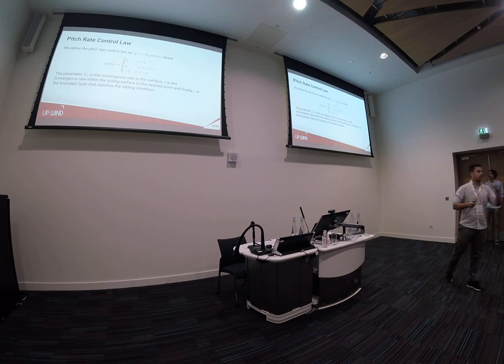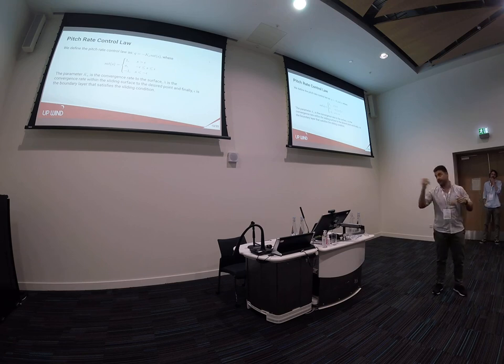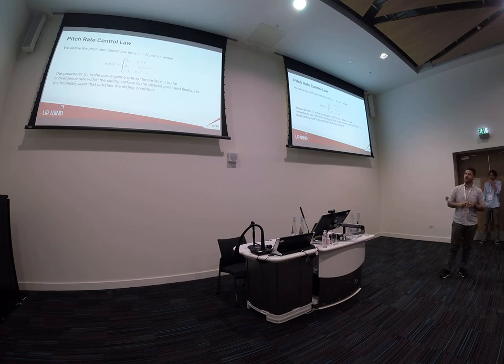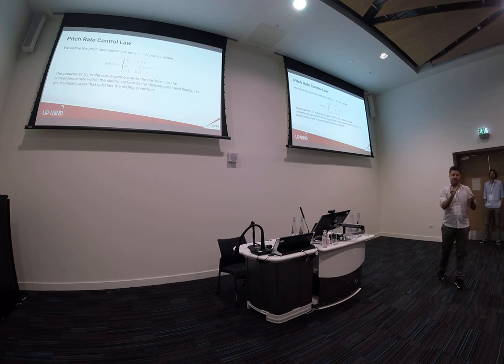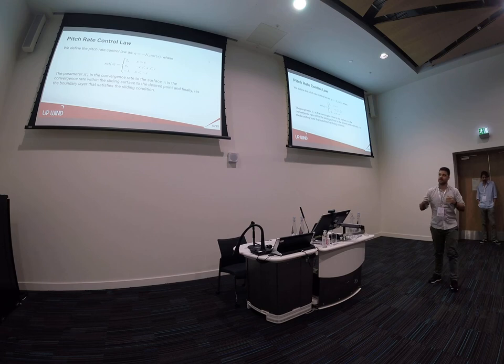Because when we are close to this surface, we don't want to always have chattering of the control, and so we define this function. If we are within a certain boundary eta, we consider exactly the surface that we are on, and if we are outside, it is exactly the other way.